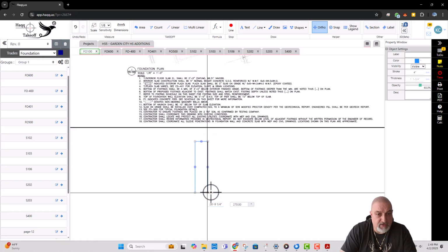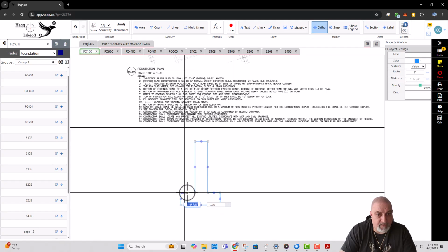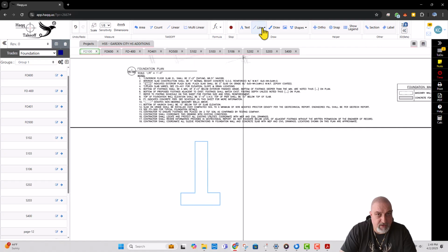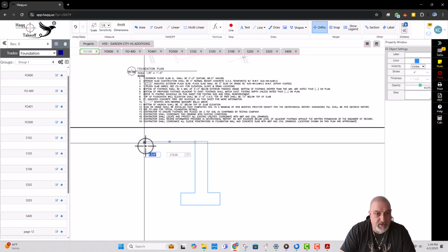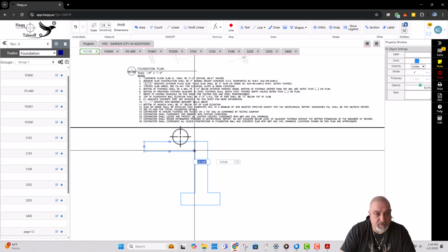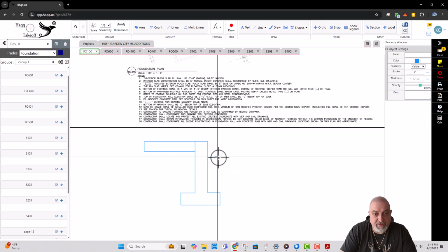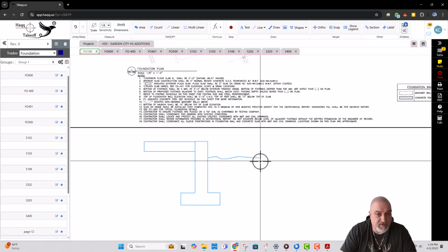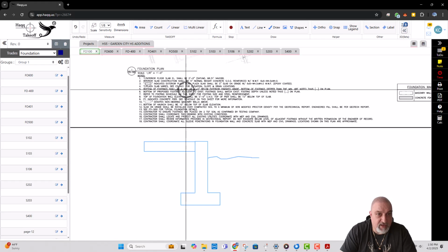Let's say this is the wall with the footing, and when you press L, it gives you that automatically. And this is the top slab, the 5-inch slab we have, and this is the exterior grade. They are talking about bottom of footing shall be a minimum of 4 feet below exterior finish grade.